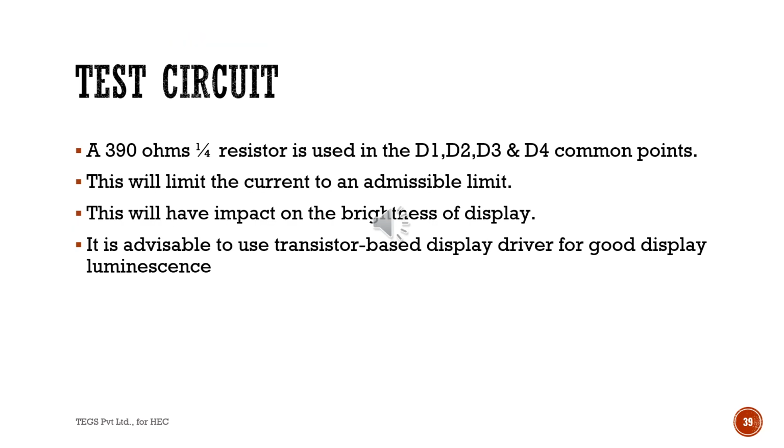The test circuit. A 390 ohm quarter-watt resistor is used in the D1, D2, D3, D4 common points. This will limit the current to an admissible limit. This will have an impact on the brightness of the display. It is advisable to use a transistor-based display driver for good display luminescence.